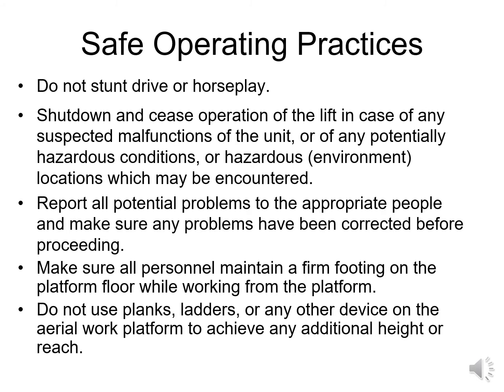Safe operating practices continued. No stunt driving or horseplay. We want to shut down or cease operation of the lift in case of any suspected malfunctions of the unit or of any potential hazardous conditions or hazardous environment locations which may be encountered.